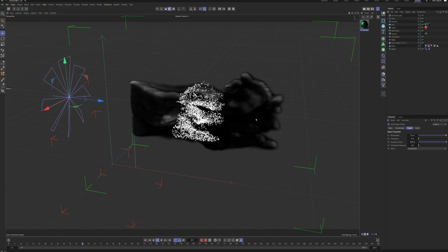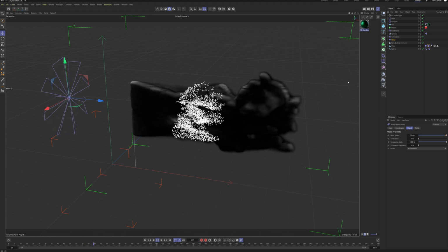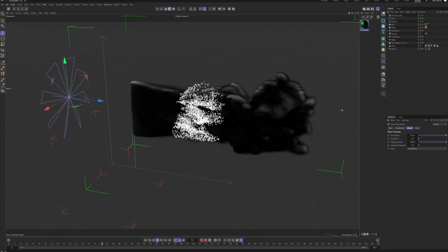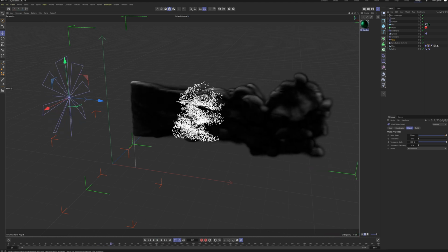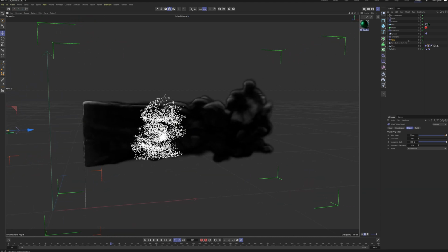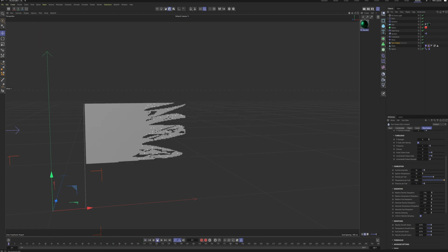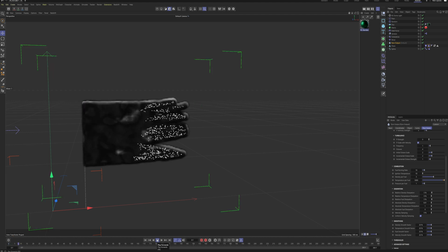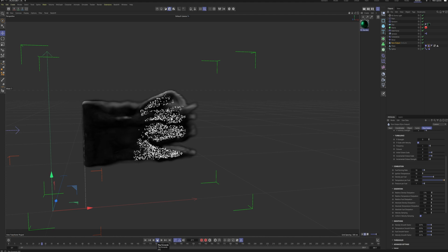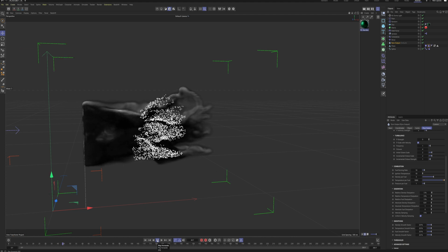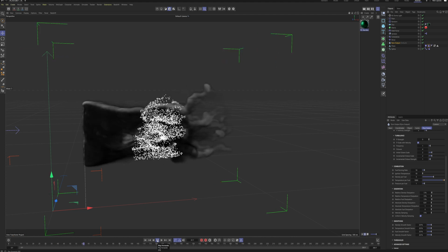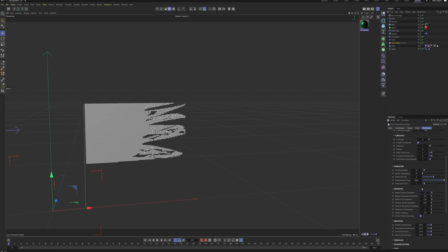And actually, since all of the particles are going to stop out here, as they also did in the foundation one, I think I'm just going to make it disappear again. So I'm just going to go in here into my pyro output, and I'm going to set the density dispersion to 5%. And let's see what happens. Oh yeah, that's way too much, I think. But let me just see when it gets going. Yeah, that's a little bit too much. So let's set it to 2% then.